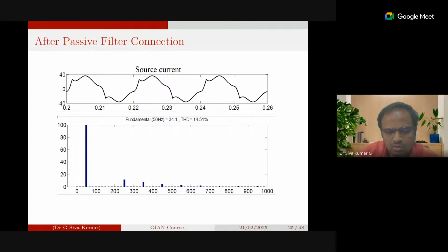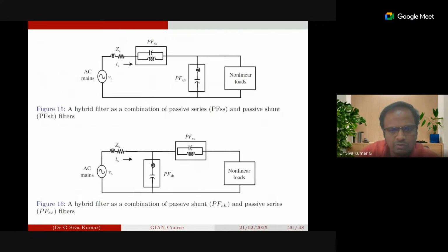In the microgrid, in day-to-day life you have different kinds of power electronic loads or nonlinear loads, so these kinds of currents will also be there in a system. The first major impact when you allow the nonlinear current in a system is that we are going to underutilize the system. It is seen by observation of the power factor. Power factor is going to reduce.